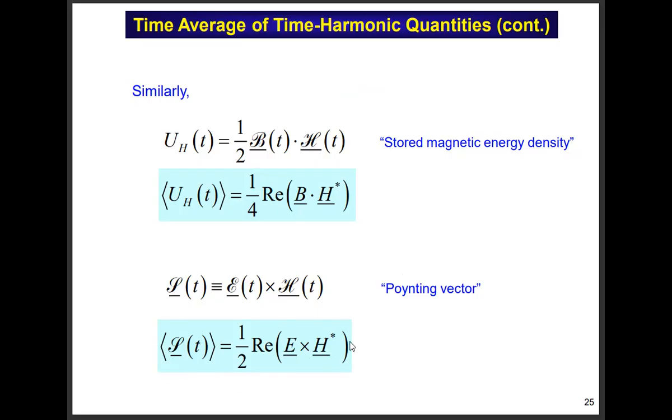So the time average power flow in any EM field, assuming that E and H vary sinusoidally, which is what we're assuming with all this time average stuff, is going to be 1/2 the real part of E cross H conjugate, phasor E, phasor H. Now, this is a vector. The direction of it tells us the direction the power is flowing in space. For example, if a wave is coming from that satellite going this way, the power is flowing in that direction. But then the time average tells us the watts per square meter flowing in the wave. We'll prove that in notes 5.